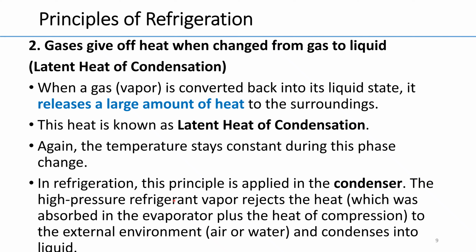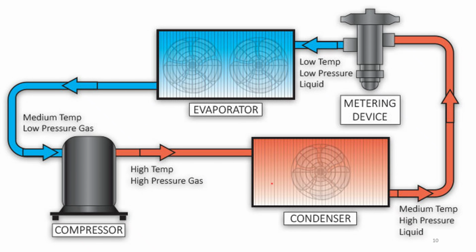In refrigeration, this principle is applied in the condenser. The high pressure refrigerant vapor rejects the heat which was absorbed in the evaporator, plus the heat of compression, to the external environment and condenses into liquid. So this is the overall theme of a refrigerator.